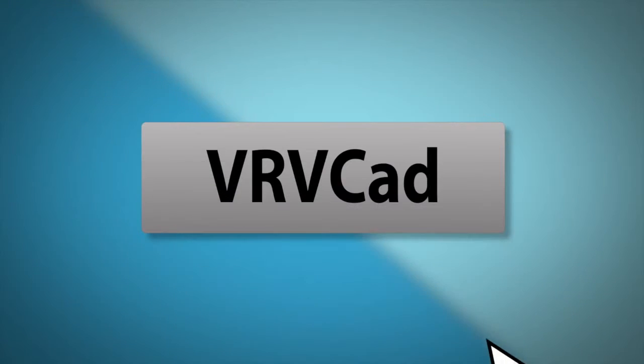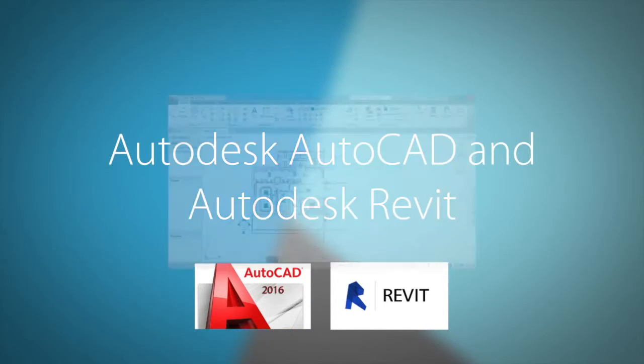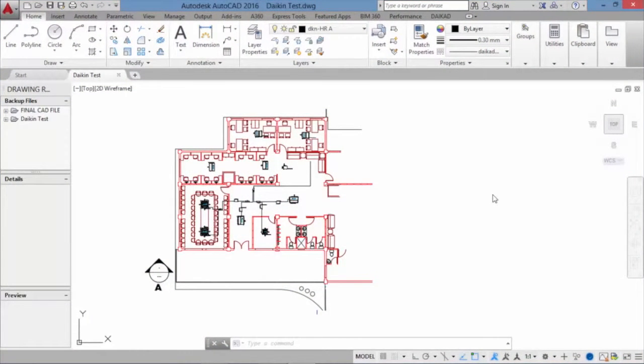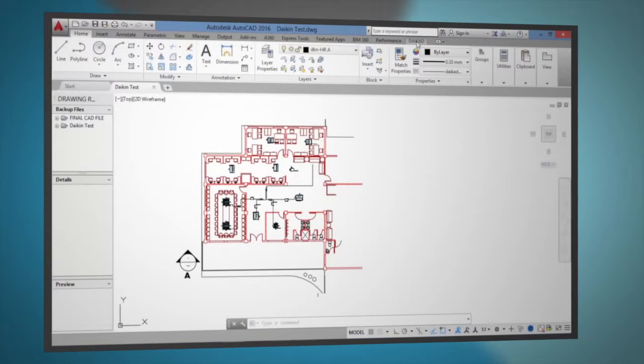To help in this task, DAIKIN have developed VRVCad, a 2D and 3D VRV plugin for commonly used Autodesk products that will significantly simplify this process. We like to think of it as DAIKIN aided design. The VRVCad plugin allows you to drop the correct indoor and outdoor units onto your CAD schematic and draw in the pipework and ref nets. This example shows how it works in AutoCAD.